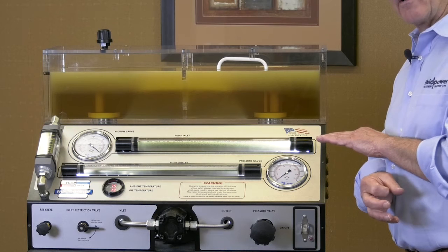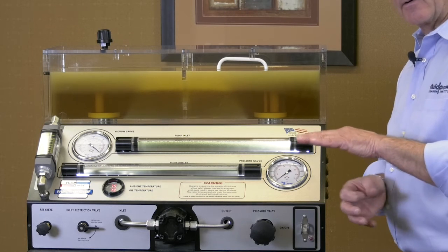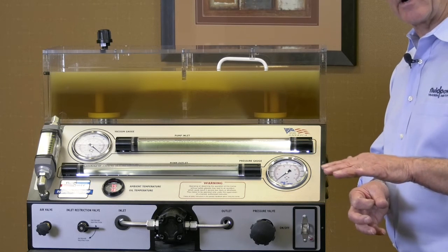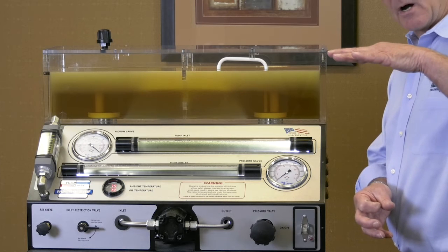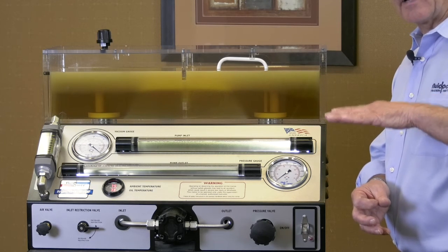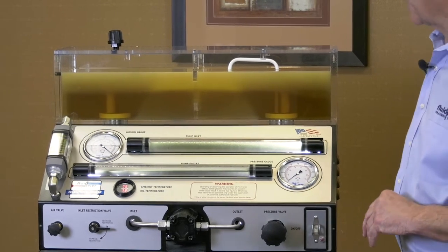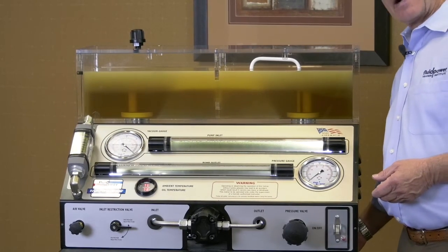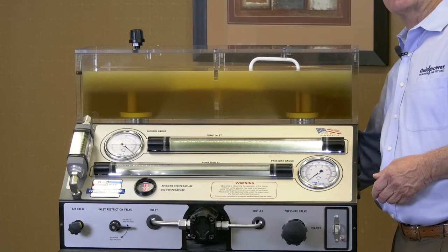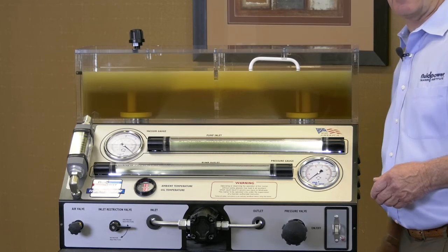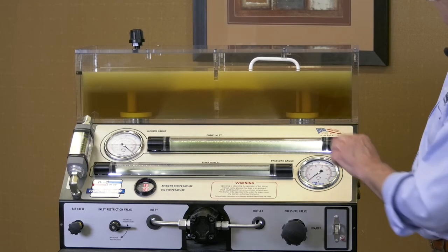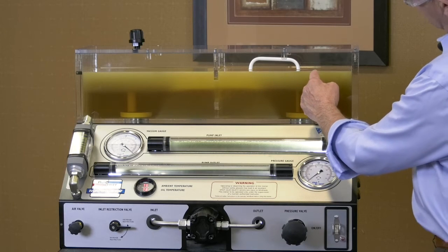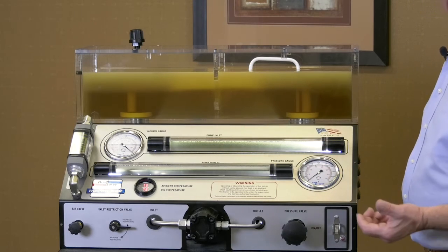So no oil that is flowing, or return line that is flowing oil, should ever discharge above the oil level in a hydraulic reservoir. For this demonstration, I'm going to open a valve at the back of the simulator, which is going to start to drain the oil out of the reservoir. The white tube inside the reservoir is the return line.